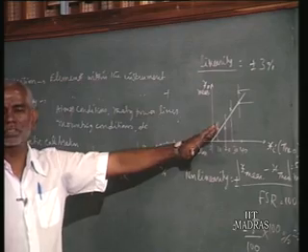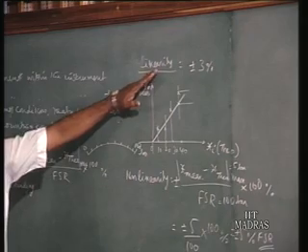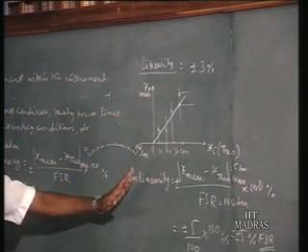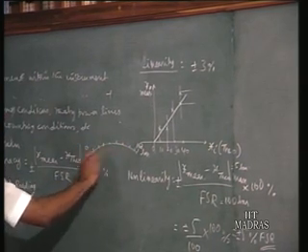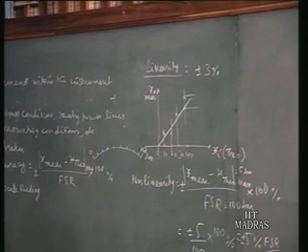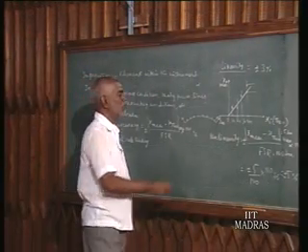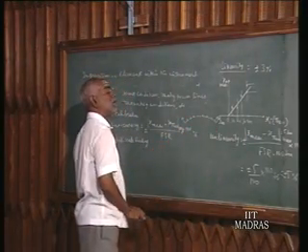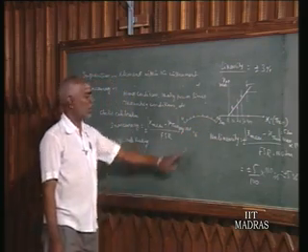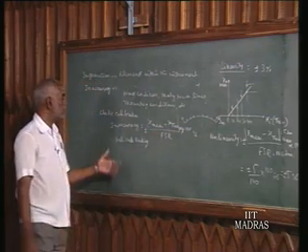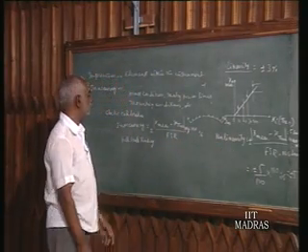Most of the monitoring type of instruments will be linear in characteristics. The scale will be uniformly distributed; the distance between two consecutive readings will be the same. That is a linear scale. And there are instruments, for example a flyball speed measuring instrument using the flyball principle, where the readings will be crowded near the end of the scale. It will not be uniform. They are the nonlinear instruments. For nonlinear instruments, the inaccuracy is given. For linear instruments, nonlinearity is given. That is how these two things are made use of.